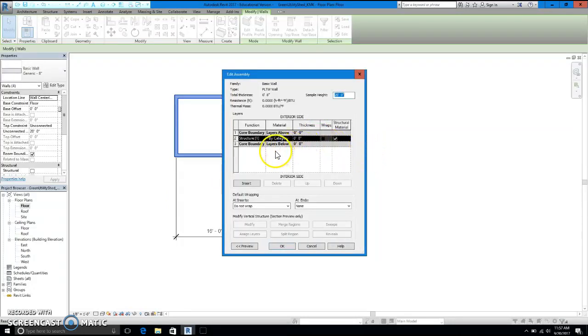And you're going to have a couple options here. You'll see first off that the thickness is 8 inches. That means that the lumber used to support this wall is 8 inches thick, which is a 2 by 8. That is too much. We're building a shed, not a skyscraper or anything big, and so I can make this a lot smaller, which is a lot more cost effective.